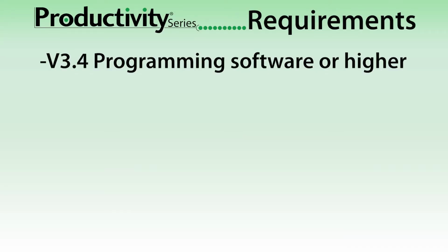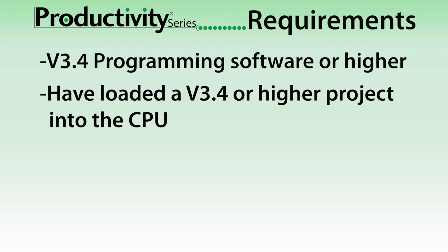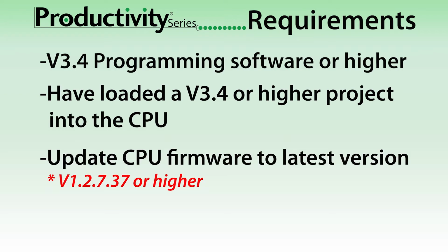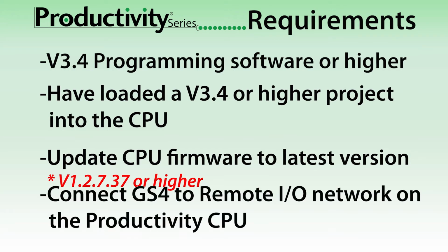You must have at least programming software version 3.4 or higher and have loaded a 3.4 or higher project to your CPU. Then update the firmware on your CPU to the latest version. Connect the GS4 to the remote network port on the Productivity.